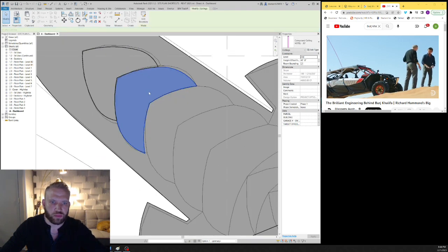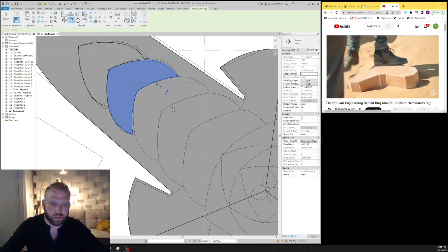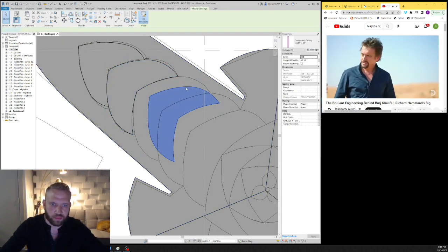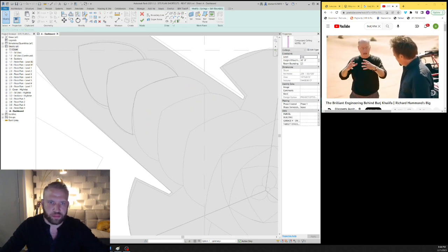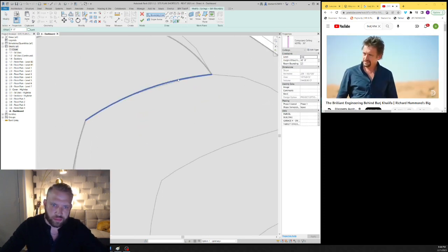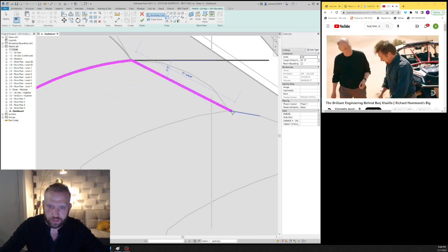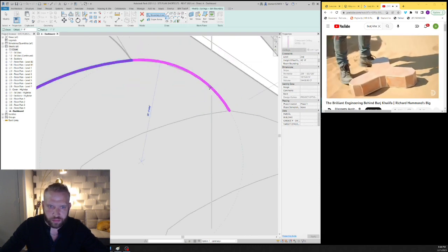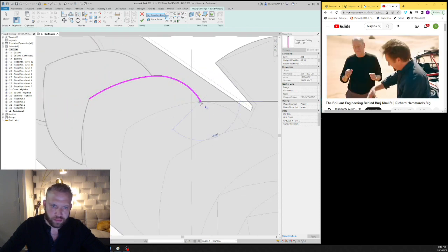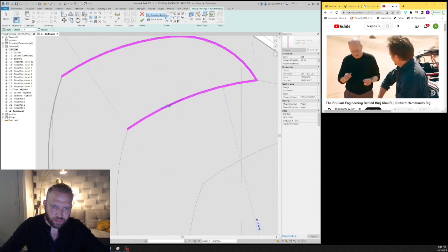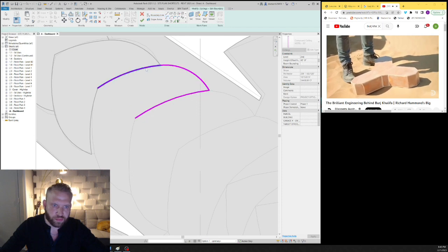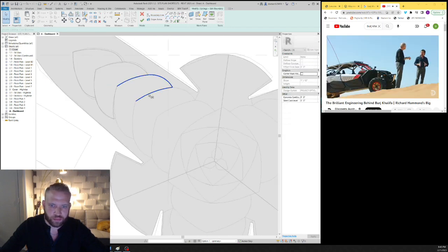Right. But there's a bigger problem. What's stopping it falling over? Below this, we drilled 194 shafts of concrete into this calcisiltite. So in the simplest possible terms, it doesn't sink because it's on this giant sand shoe. And these piles, they're still in effectively sand. Yes. So the thing that's holding it up is friction.